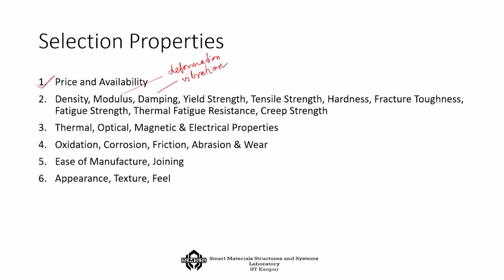Then there is yield strength, and two strengths we have talked about here. One is the yield strength and another is the tensile strength. Of course, tensile strength you know is specifically guided towards the tensile force resistance of a material, and the yield strength actually talks about the point beyond which you will get irrecoverable deformation in the system, which we also say plastic deformation. So, we do not want to go beyond these points.